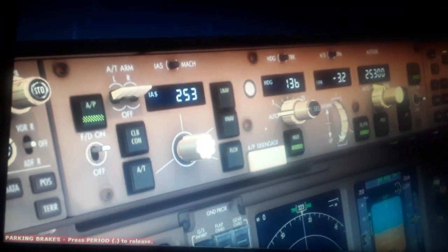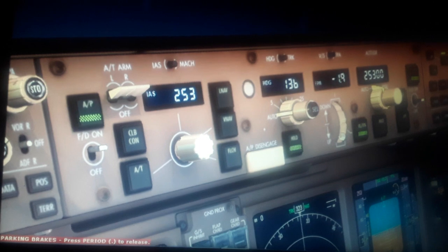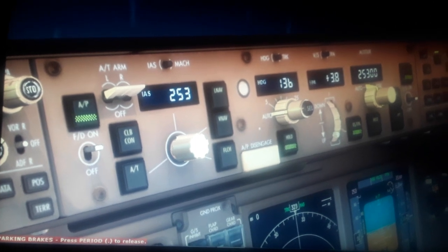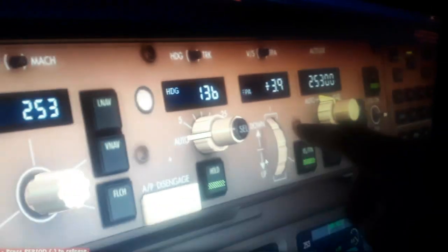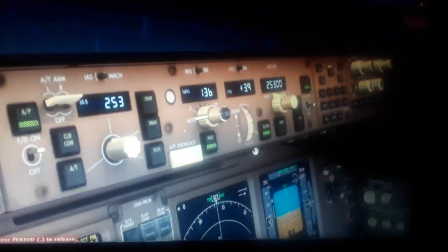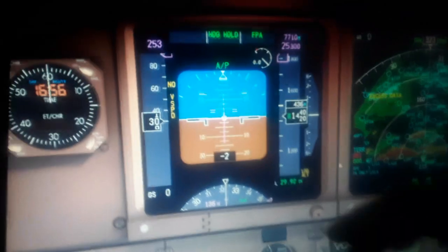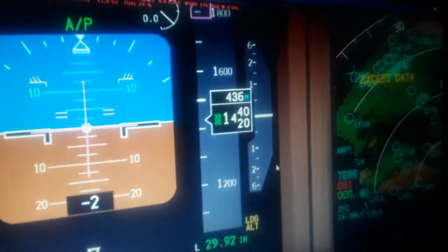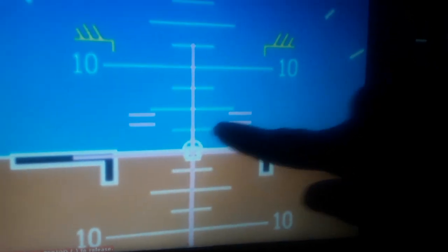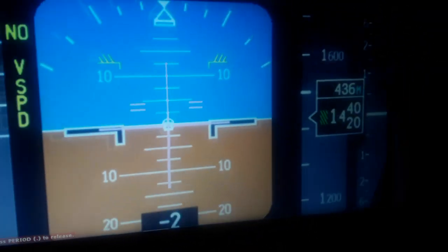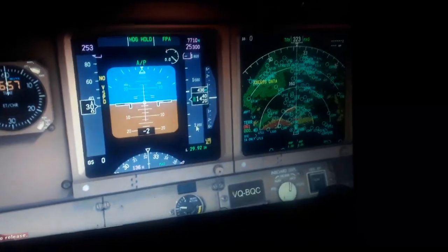You will see the other way. We're gonna move the slider. So moving the slider this way, up or down, changes the indicated value, now for climb to 3.9 degrees. Over here, and you see the pitch ladder. This is gonna guide the autopilot, the flight director guidance.